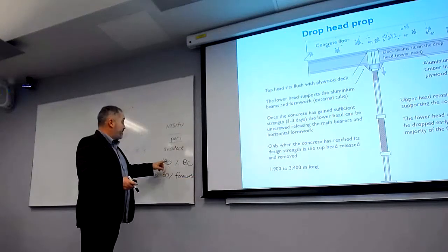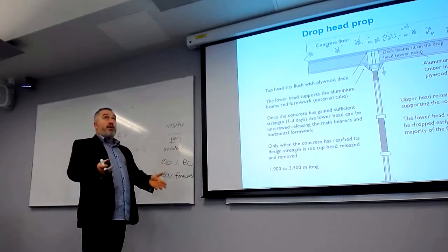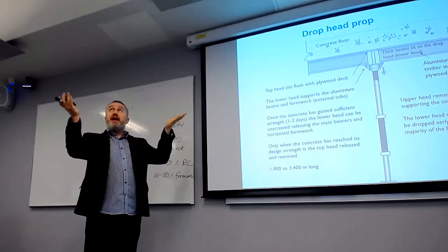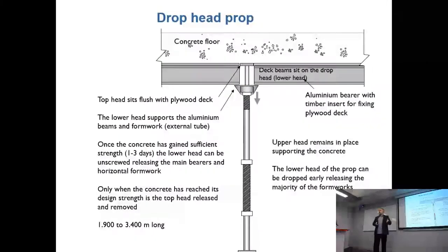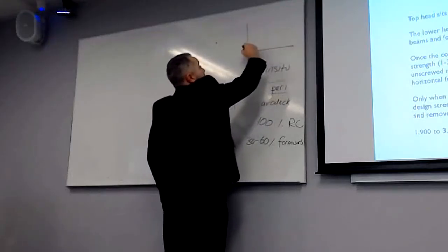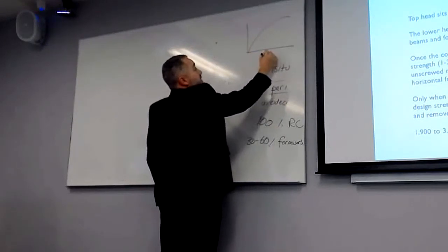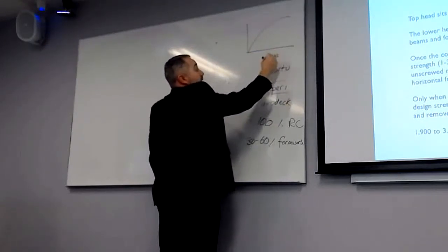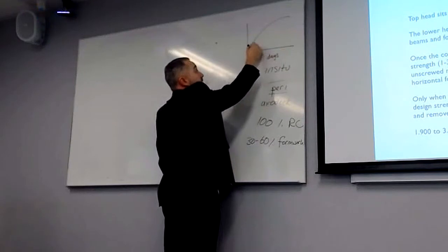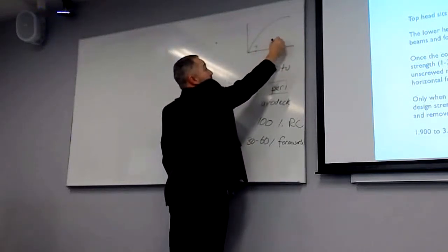Plus, this formwork, they put it in place and they don't keep it there for long. Do we know how long it takes for concrete to go off? Have you covered concrete in materials yet? I think maybe it's next week, week 16, if you're covering concrete. But in terms of concrete, it increases in strength over days. And what we tend to measure is day 7 and day 28.